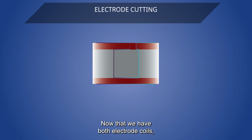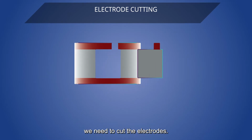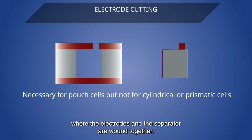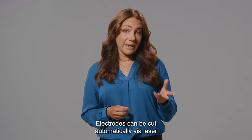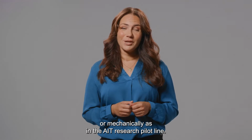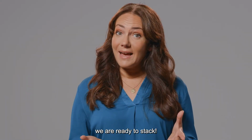Now that we have both electrode coils, we need to cut the electrodes. This surely is necessary for the pouch cell prototype presented in this video, but not in the case of cylindrical or prismatic cells, where the electrodes and the separator are wound together. Electrodes can be cut automatically via laser or using pressurized air, as in the AIT Research Pilot Line. The electrodes are set. We're ready to stack.